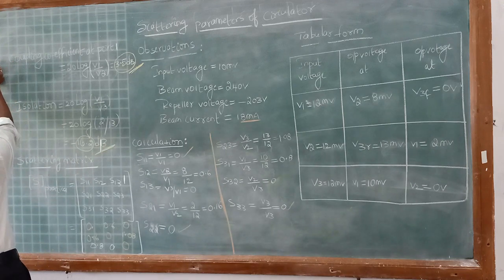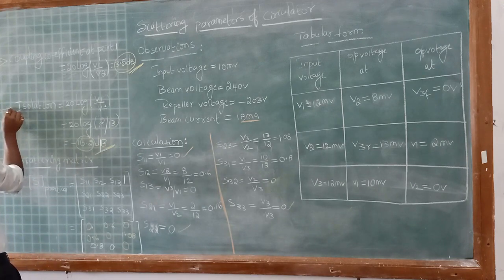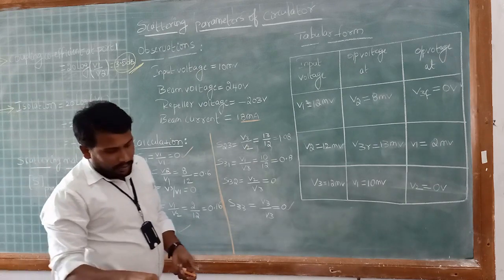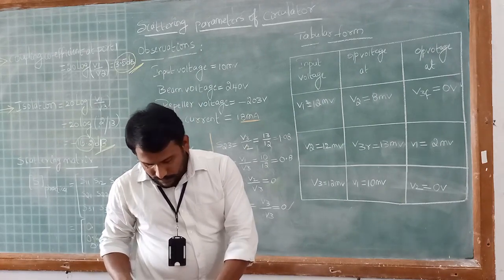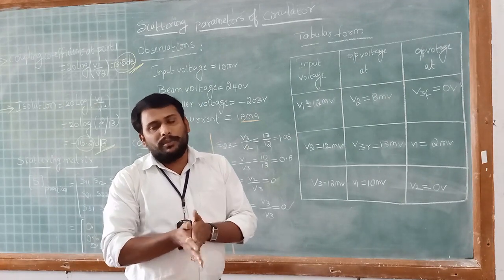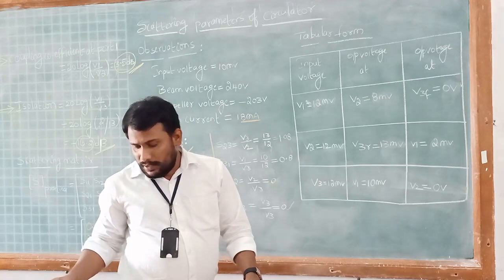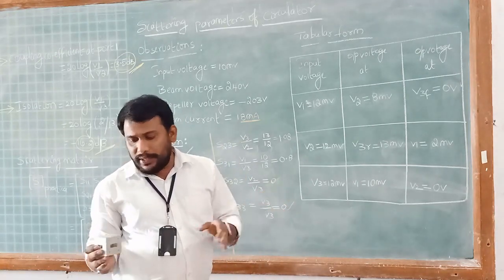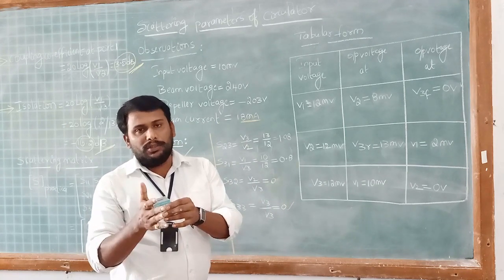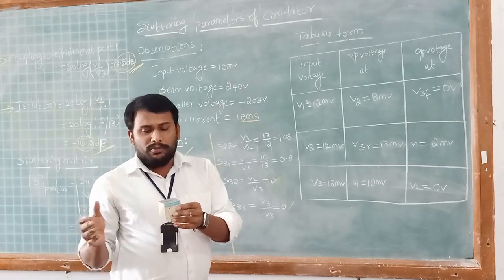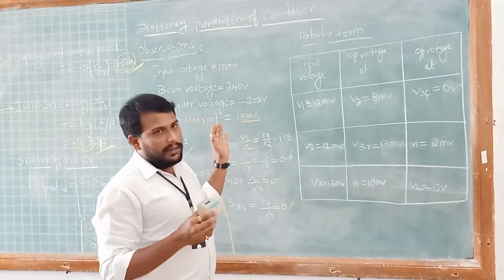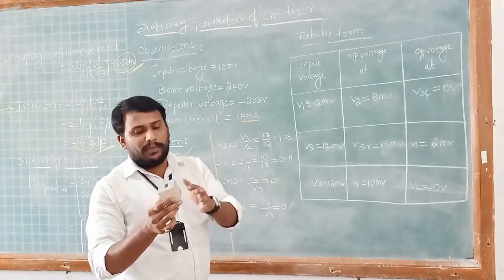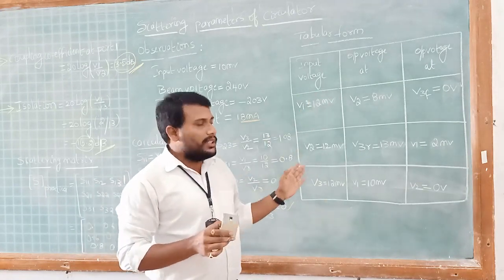So coupling coefficient and isolation are the values we need to find out, and this is how you have to perform the experiment in the laboratory. Initially you have to connect the circulator to a detector mount. Without the circulator, find the power or voltage, and after connecting the circulator in different combinations, find the voltage values.